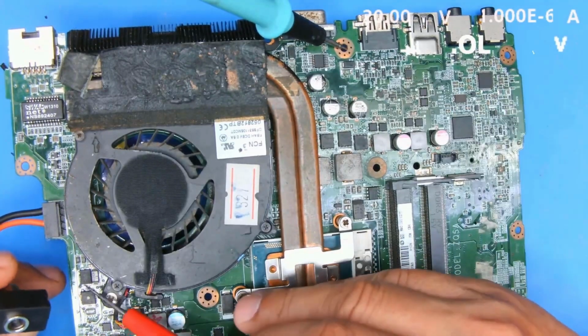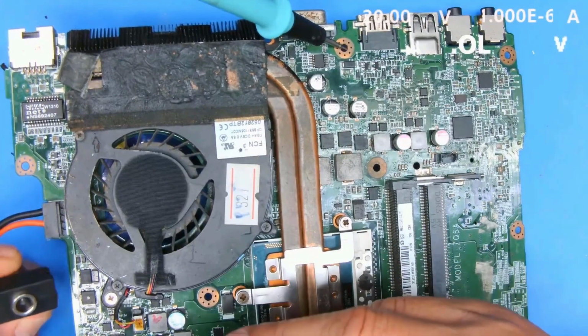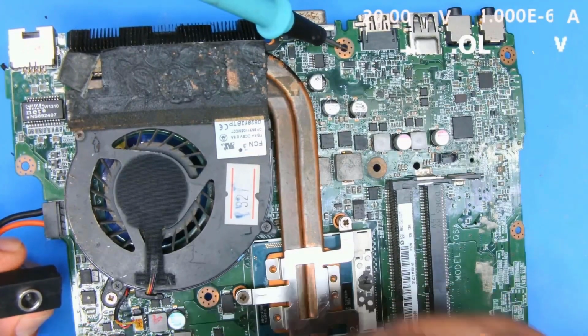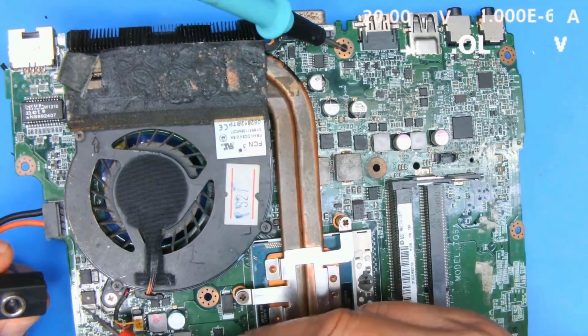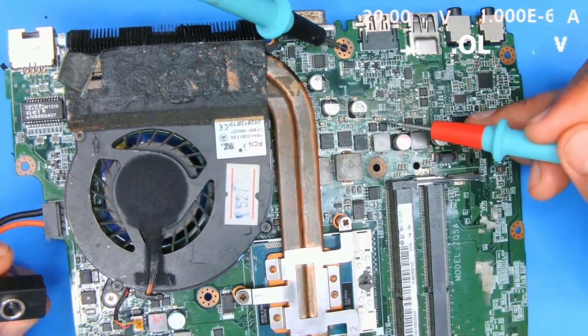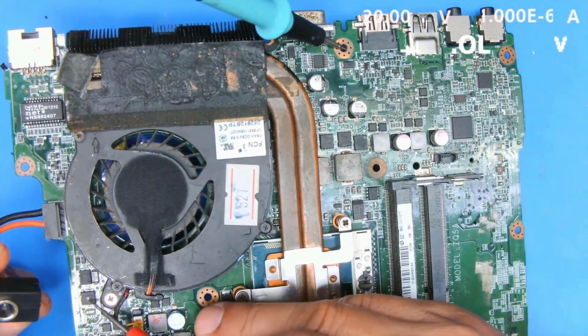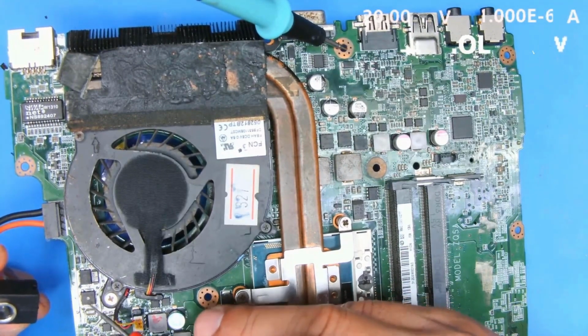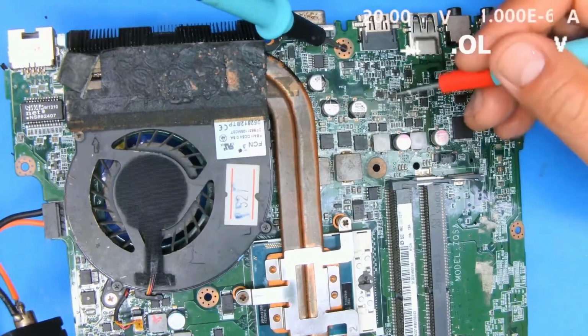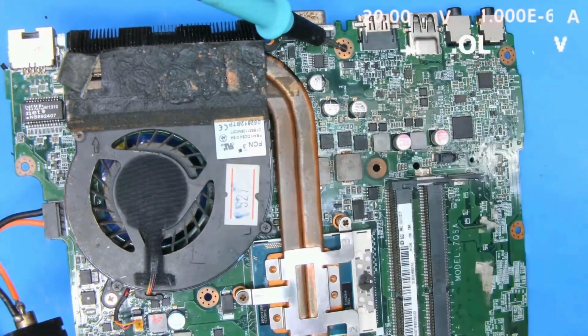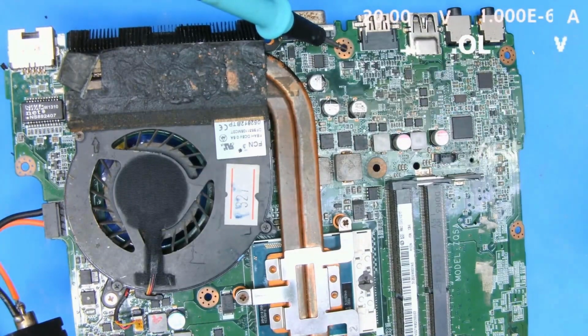If we supply power here to find the short or the hot component, it can cause problems because the power will pass through the MOSFET and this power control unit and then go to the series short, which can cause the MOSFET here to short as well. As I mentioned earlier, the device works normally but doesn't charge the battery. Remember, it doesn't charge the battery. Now, what we need to do is inject power at pin 49 instead, which is the safest method.